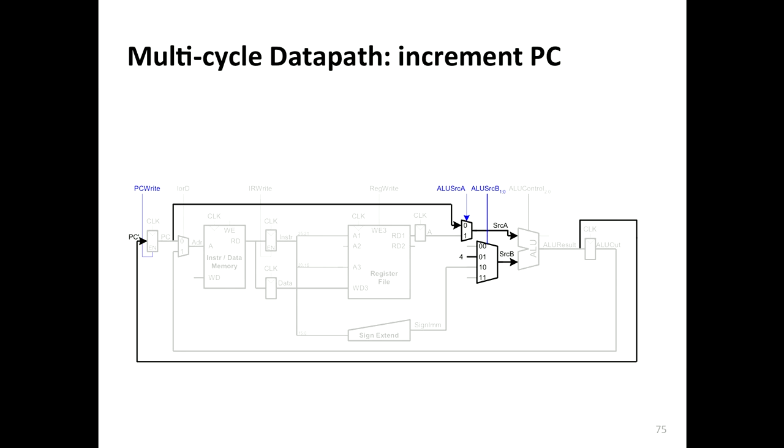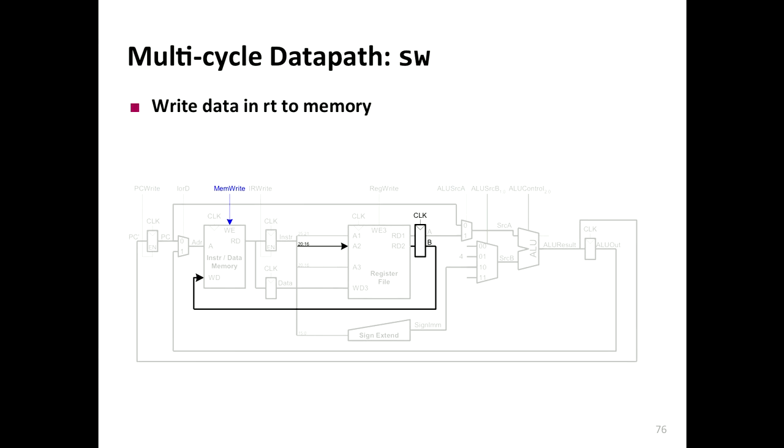So in this stage, these control signals need to be set. Okay. So store word, you need to provide more data path until you exhaust everything in the ISA, of course, right? For store word, you need this data path on top of what we've had for the load, because store is very similar to load. You just need to be able to do the store over here.